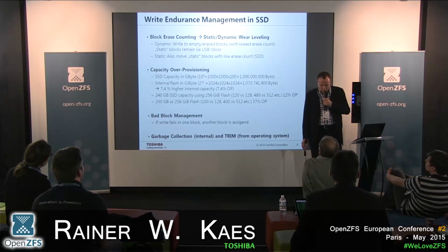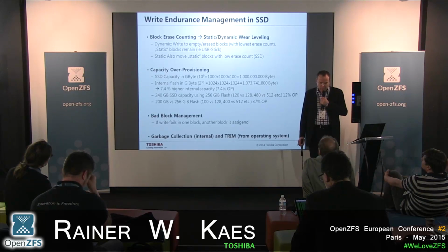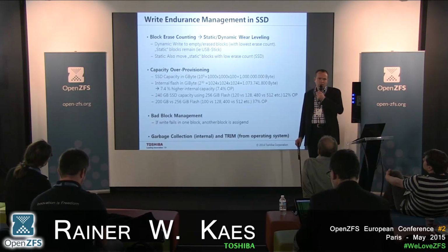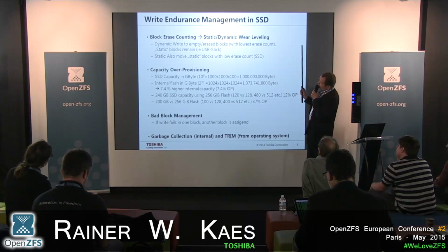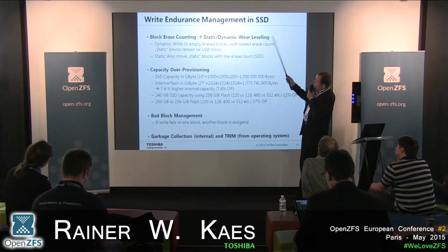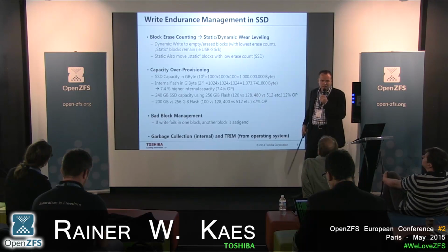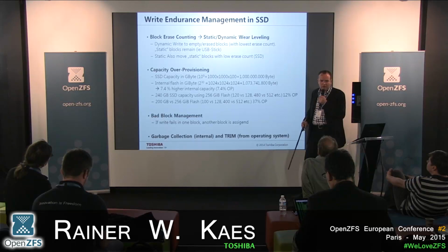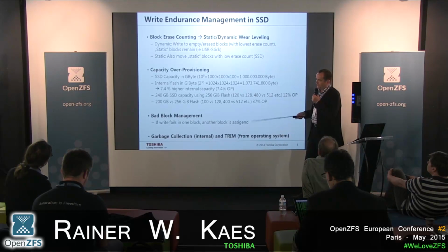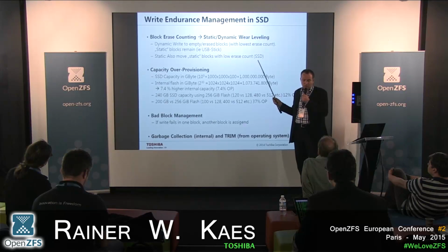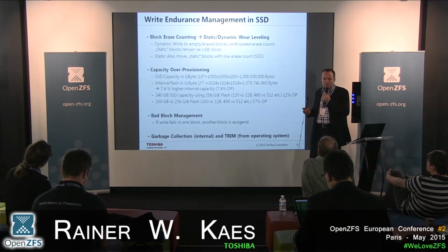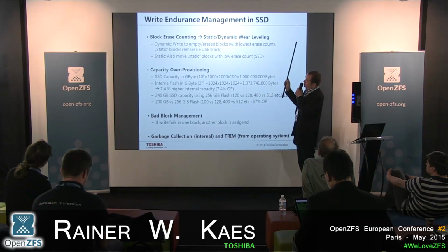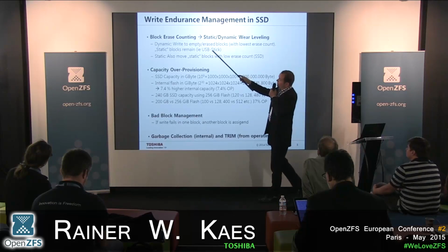So what do we do so as not to bother the user with the write endurance or erase endurance issue of the single flash cell? First of all, we need to do wear leveling. In a hard disk, there's a lot of activity in very few sectors. If we did this in an SSD or in any storage component, SD card or USB stick, and you always write or erase one area, it will be erased to death pretty soon. So there is wear leveling, and wear leveling is based on block erase counting.